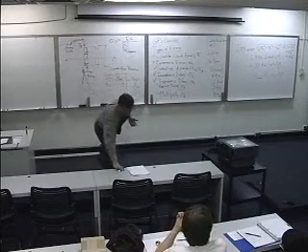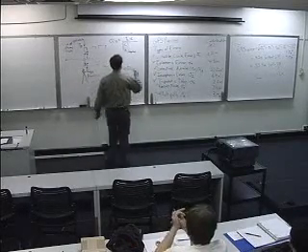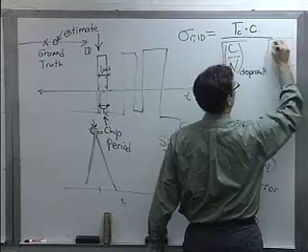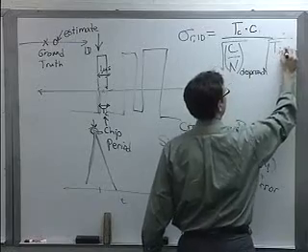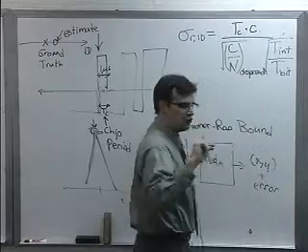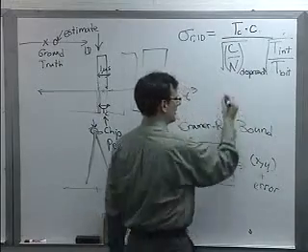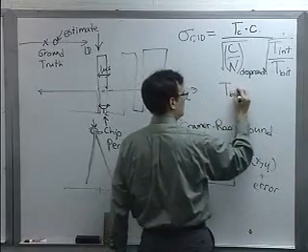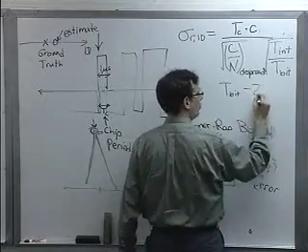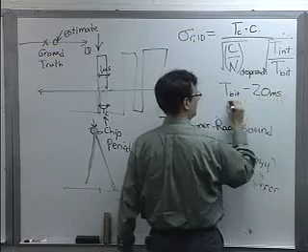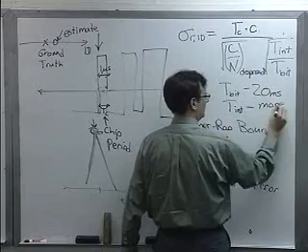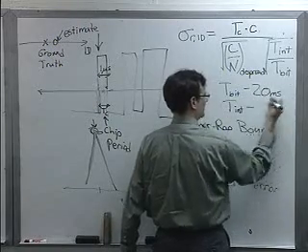And so there's another factor that you can put in here. Call it T int over T bit. So a cheap GPS receiver will integrate over 1 bit period, 20 milliseconds. Let's call this the averaging interval.